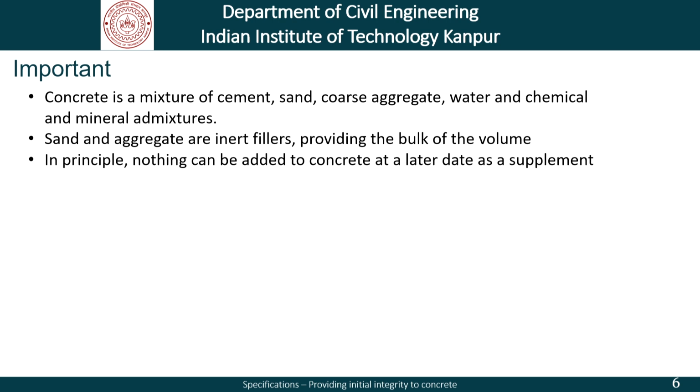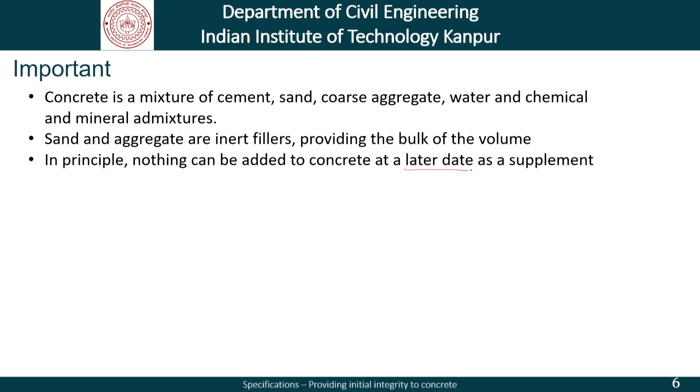In principle, nothing can be added to the concrete at a later date as a supplement. So, whatever we want to add in the concrete has to be added at the time of mixing, and it becomes an integral part of the concrete. At any later date, it is more or less impossible to add something to any kind of concrete.